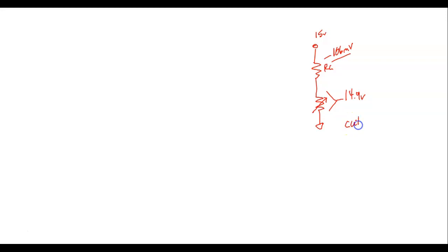Now, what you have to understand, a transistor is not an open switch. A transistor is a transistor. There is a path for current to get through there. So even when it's cut off, it will not drop the applied voltage entirely. So this is just current that's leaking through it, right? You understand that? Yes or no? So it's cut off. Yep. We say it's cut off, but there's always a path.